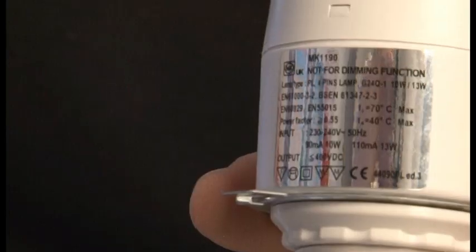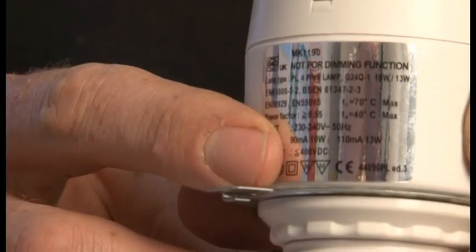Sometimes it's as easy as looking for the familiar double square symbol on Class 2 equipment, but reinforced insulation is a little trickier. Although this appeared in the definitions of the 16th edition, it didn't appear on the schedule of items inspected, whereas in the 17th it does. Reinforced insulation is effectively insulation either in single or multiple layers, which gives equivalent protection to that of double insulation. If you're uncertain whether insulation is double or reinforced, always consult the manufacturer, or where applicable, the designer. And if double or reinforced insulation is being used as a protective measure, it's important to check that no damage is evident.